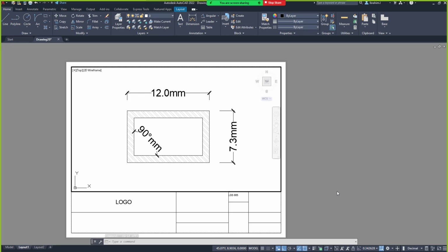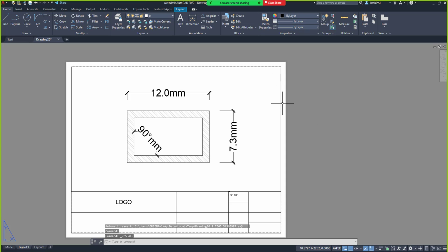Even when it's on, sir. Even when it's on, it won't show on your design now. If you print it like that, are you with me? Even when it's on, it won't show on your design. But turning it off will help you to gain clarity of what is about to come off on your paper. So that's why I usually turn it off here. Right? I double click outside, select my viewport, put it under layer 0. Why do I want to do that? Because I want to turn that line off.